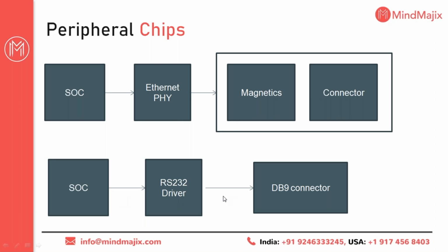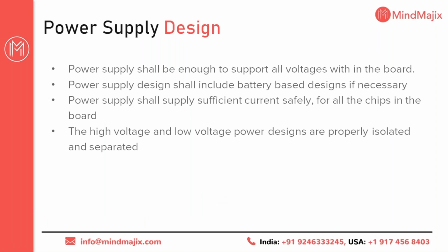Similarly, you are designing an RS-232 based board with a DB9 connector, the typical serial port connector, which is connected to an RS-232 level shifter driver that connects to the SoC. So one needs to understand how this interfacing happens. That way, not only for these two interfaces, but for many interfaces, you learn and design the interfaces.